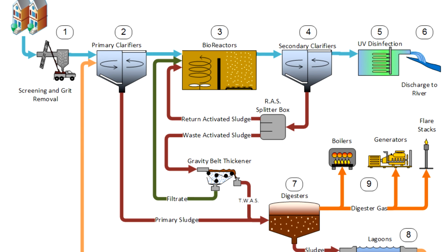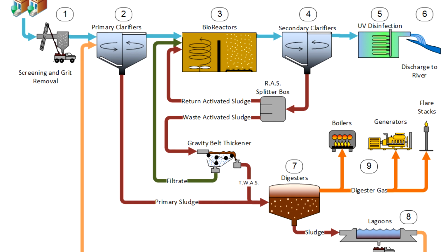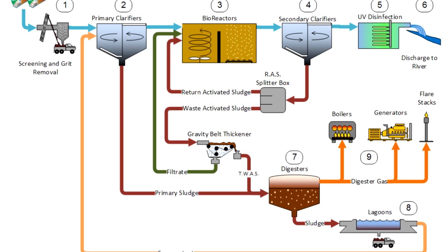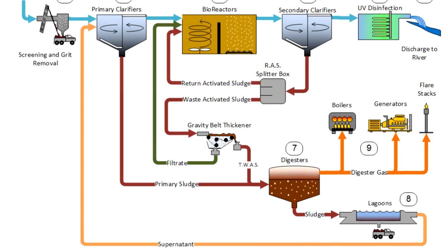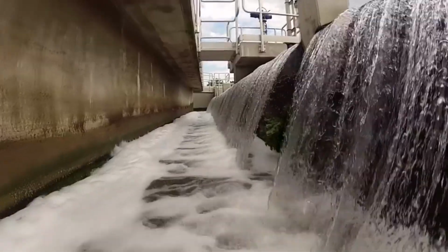On the surface of the wastewater, mechanical surface skimming devices remove grease and other floating materials. Basically, the primary system is designed to remove a significant portion of the BOD and TSS loading on a plant, thus making it easier on the secondary biological portion of the system. In general, the purpose of a clarifier is to remove solids and to produce a cleaner effluent.